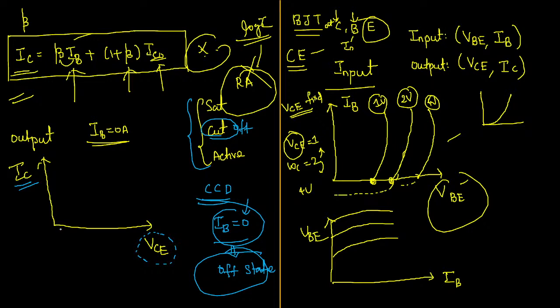It is the output terminal. What you can observe is a very less amount of leakage current flowing here. So whenever you are observing, sir, I am continuously increasing voltage but I am not able to observe the current, sir, what do you have to say? How can you observe the current, buddy? There will be no current through the base. They fixed that the base current is zero. Without base current, how will you control this? There will be no controlling action. This device will become useless. First go and give some current through the base. That can be your expected answer.